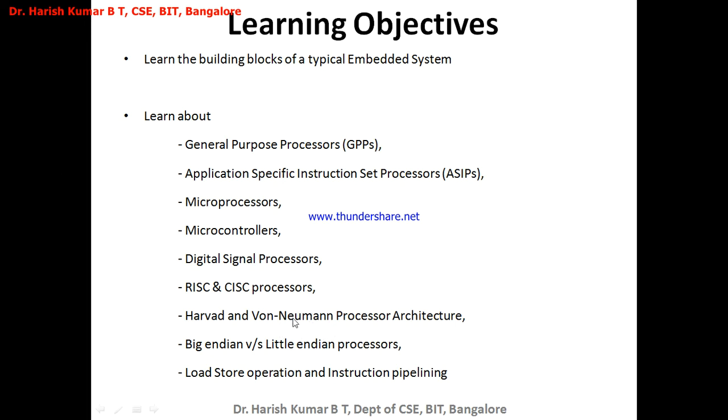Now, in the von Neumann processor, there is a single unified memory which is holding both the data and instructions, and hence a single path for both data and instructions. And later we are going to discuss byte orderness. There are two endianness types, which basically deal with the byte ordering. One is big endian byte ordering, and another one is little endian byte ordering.